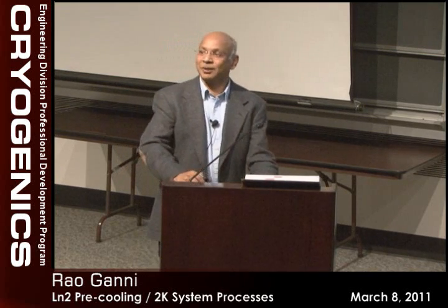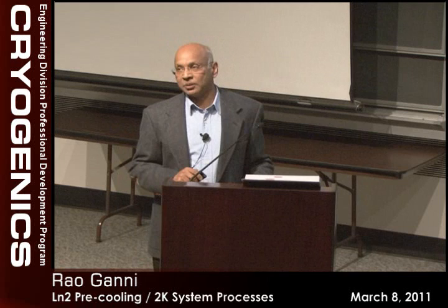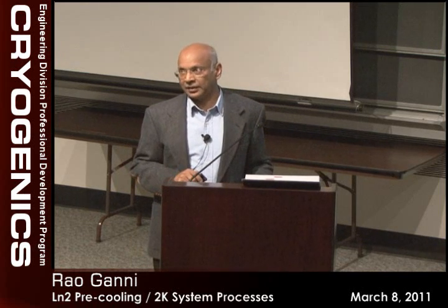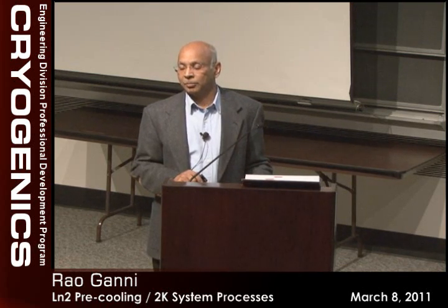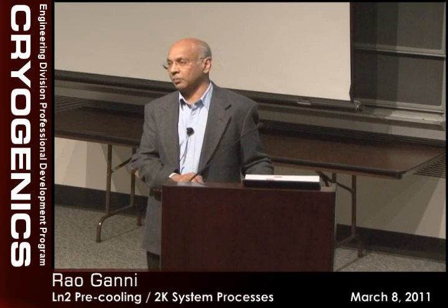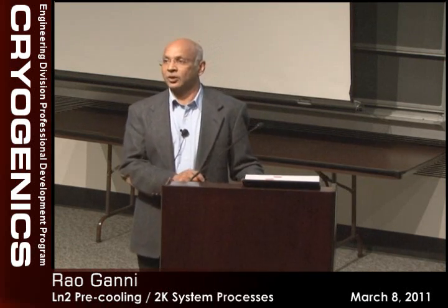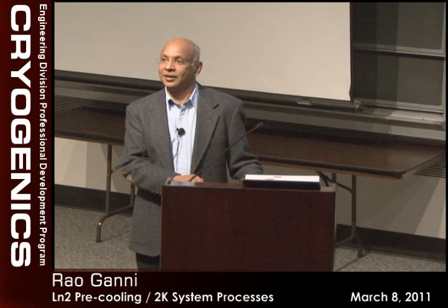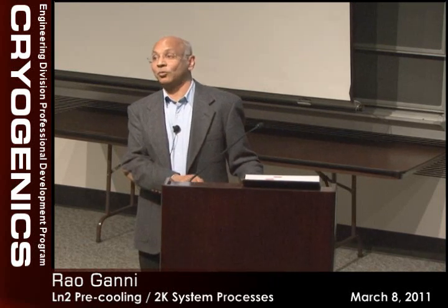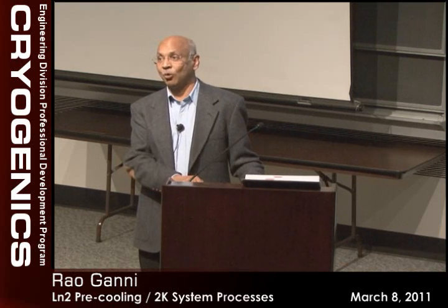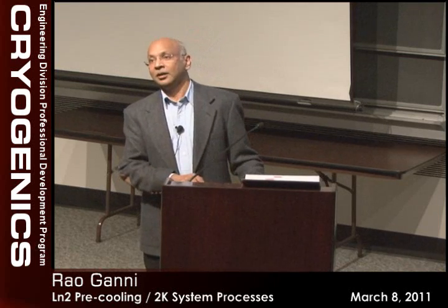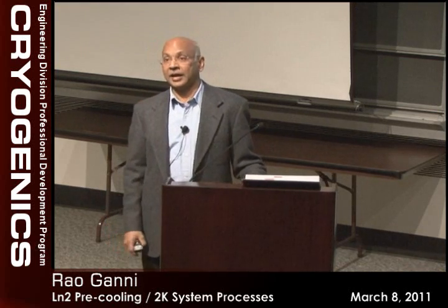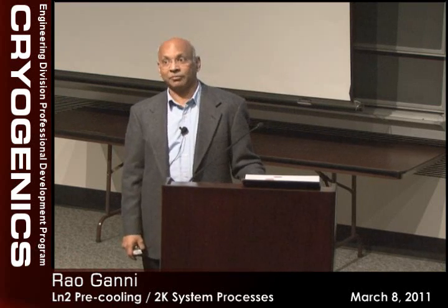But the first few days, we were very nervous because when we reduced the pressure drop on the heat exchanger in the 4K to 2K, one thing we did not recognize is the influence of that pressure on the torque characteristic of the cold compressors. By not having the pressure drop, the torque demand on cold compressor one increased, and we have no knob to turn to cut that back. We have no valves to throttle it or anything. So basically, what we had to change is the voltage versus frequency characteristics of the cold compressors, and we figured out a way.